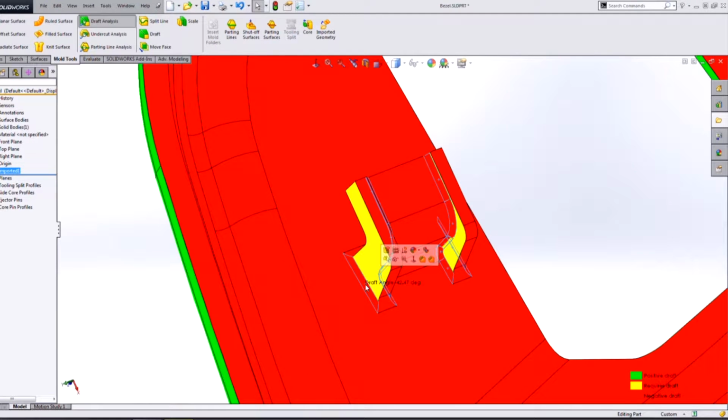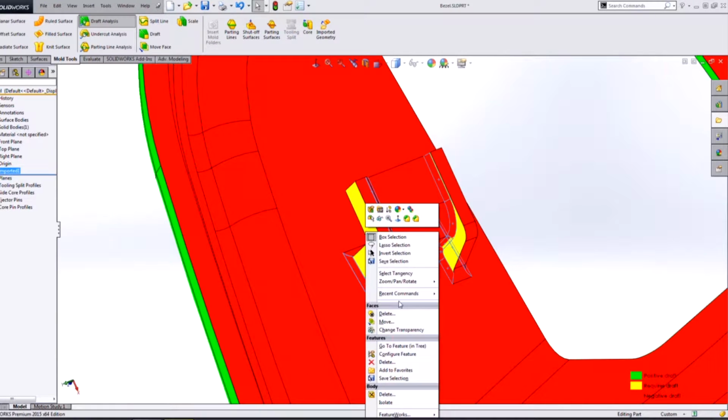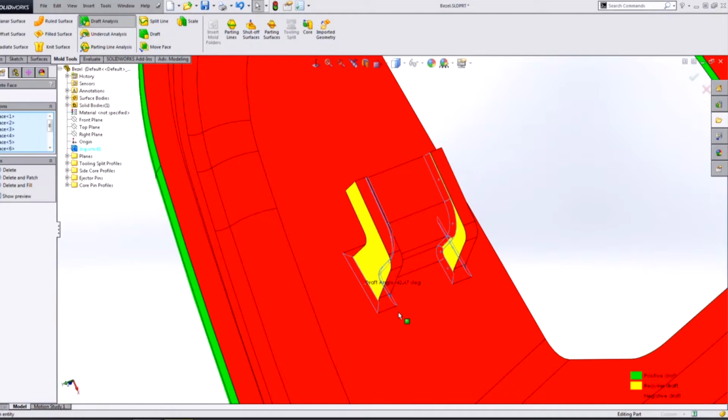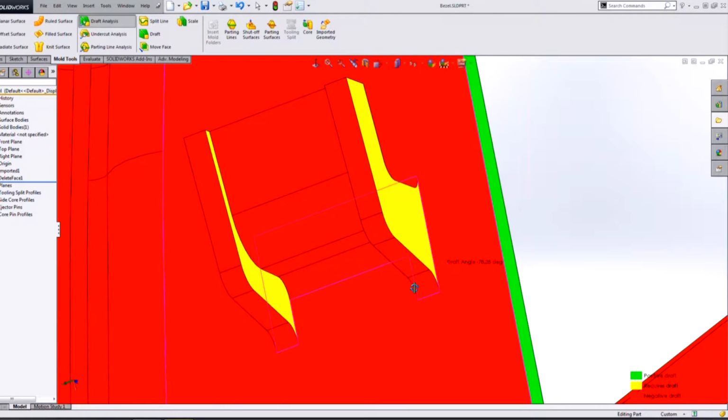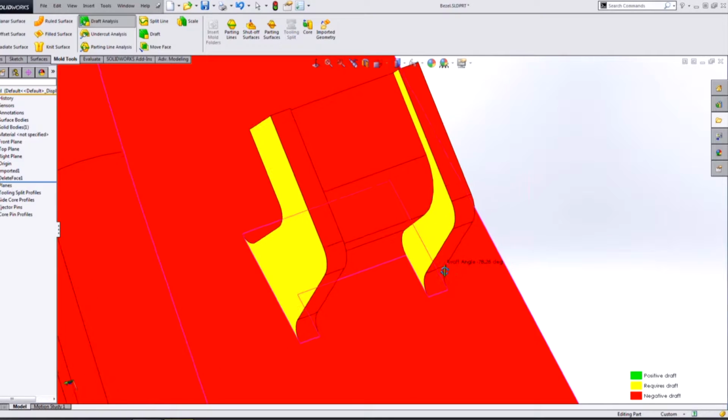And we'll get these outside ones as well. And what I'm going to do is come down to Faces, Delete, and you'll see that SOLIDWORKS gives us this option to patch, and what it's going to do is go ahead and extend the surrounding faces to a common edge, and so we're going to get our sharp corner back. And so when we say OK here, we see that it removes those fillets by direct editing, and what we get are just the planar faces.